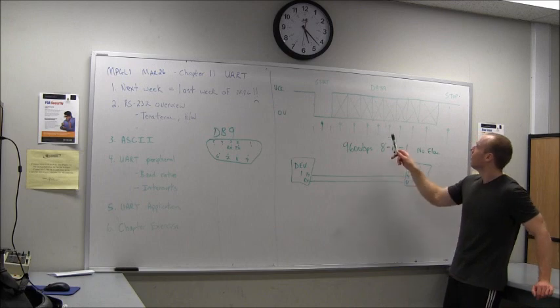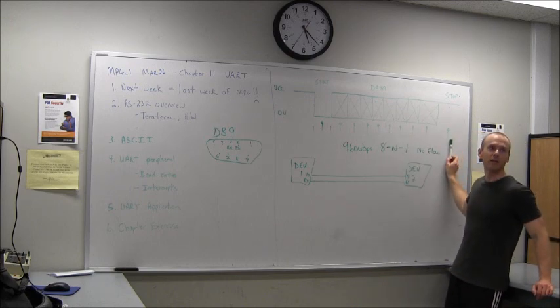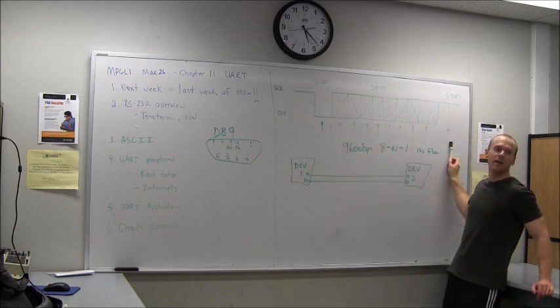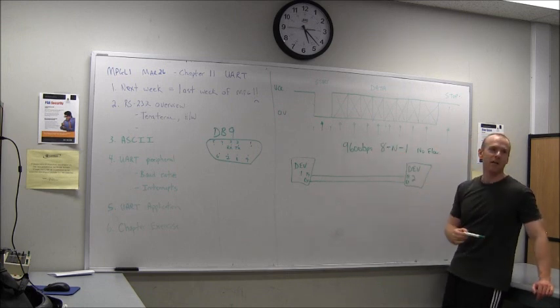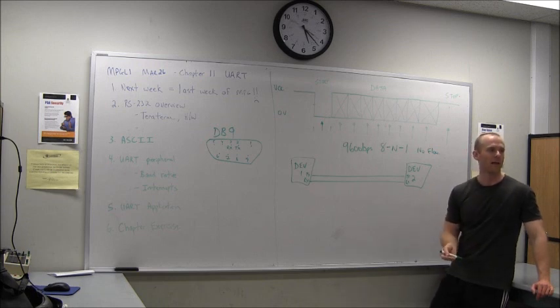And you're not going to have any problems. Once you get to this bit here, so this is the 10th bit in the transmission, it has to be high. So it's called a stop bit. So this has to be low, this sample has to be high. If that's true, that particular data byte is considered good. It won't flag any sort of error on you.